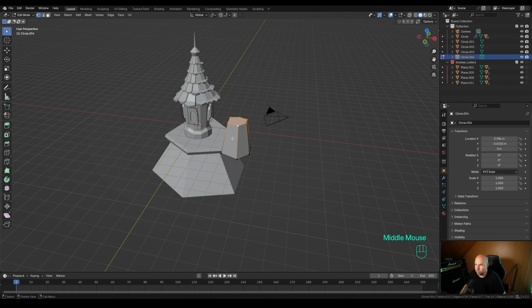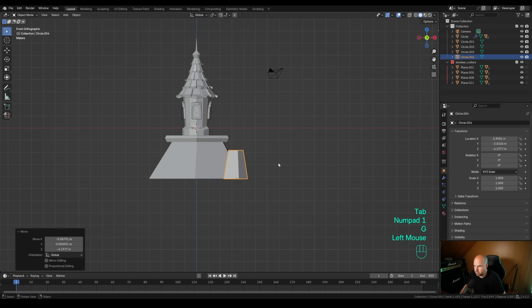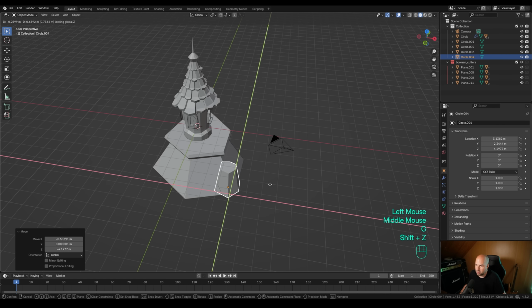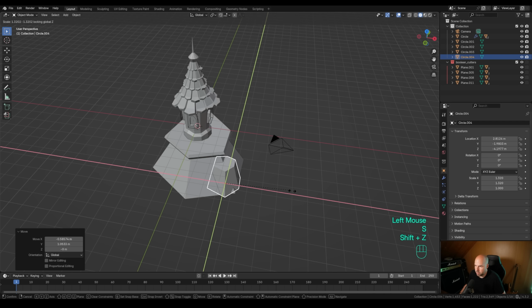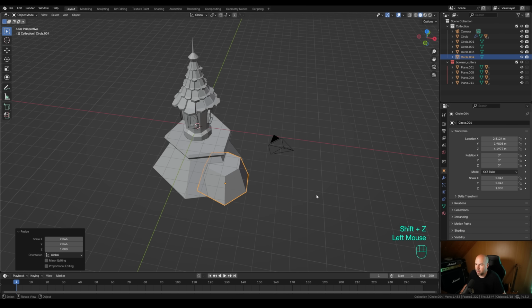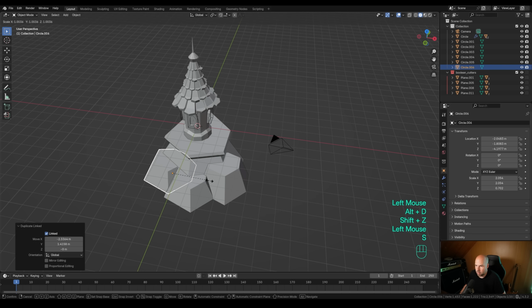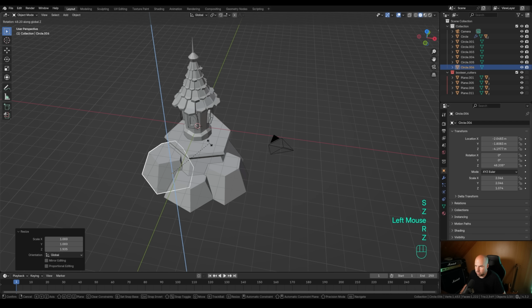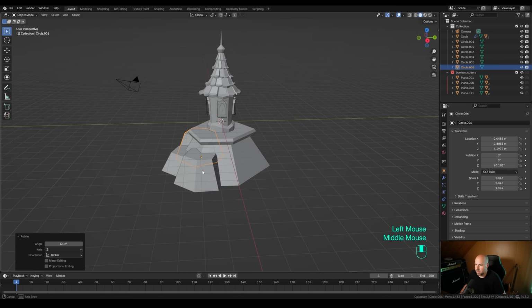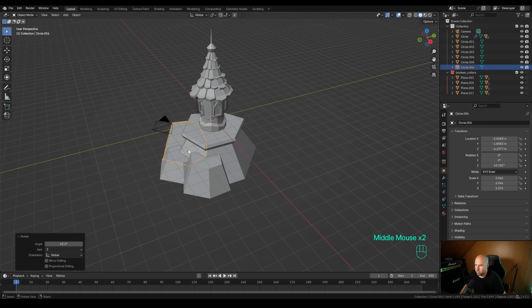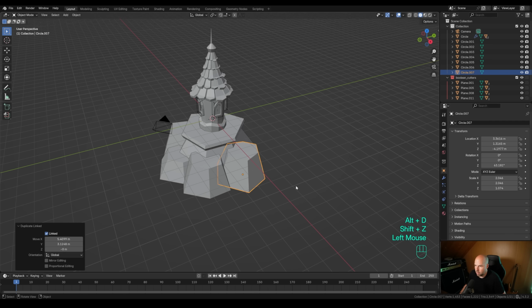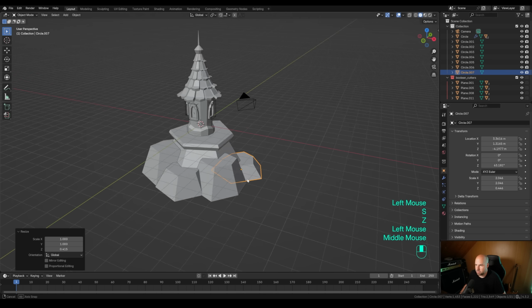And now we'll just move this around and snap it to create illusion of a rock formations basically. So let's tab out, let's look from the side, we'll move it here and we'll press G then Shift Z to move it closer here. We can also make it wider and basically just like this duplicate it. I may sometimes scale it on a Z axis. You can also rotate it. Basically whatever will help you to make this look a little bit more detailed and intricate as a rock formation.